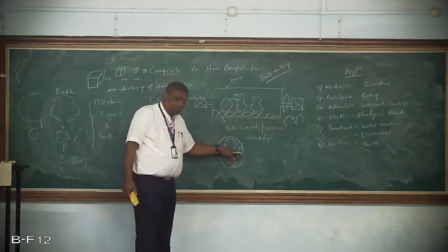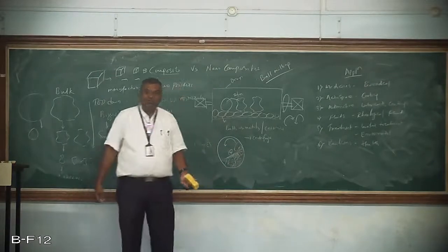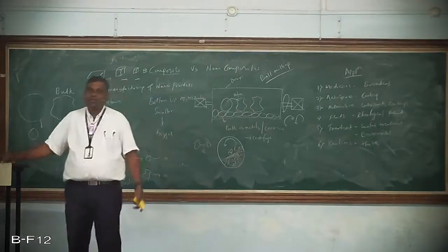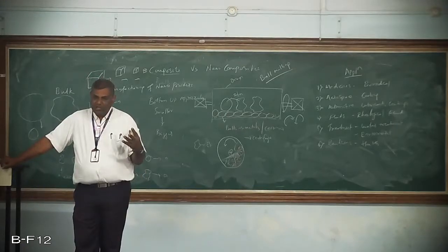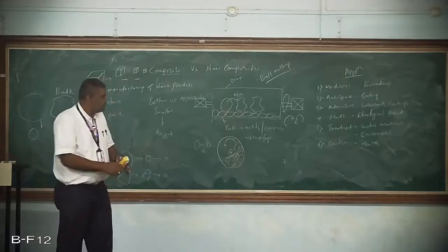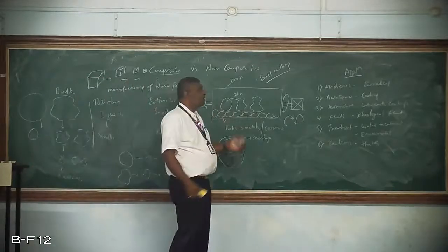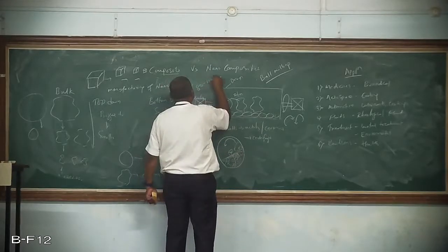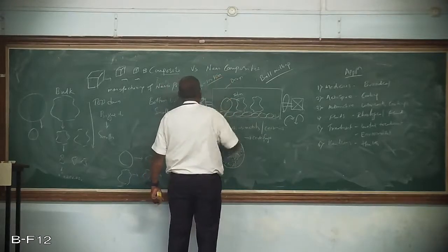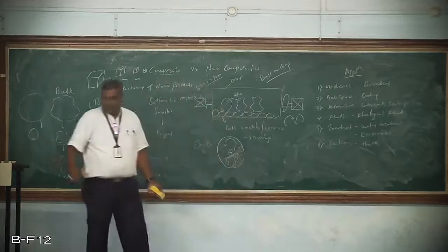Then they also put in these balls. These balls are made up of lead material. Basically lead is heavier in nature and it is very strong. So they put this material in and start the machine, and this is allowed to rotate at 80 to 100 RPM.